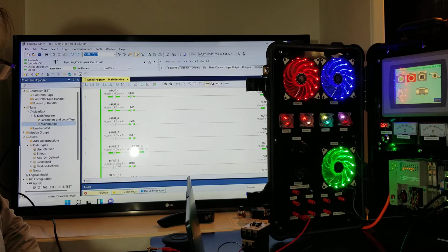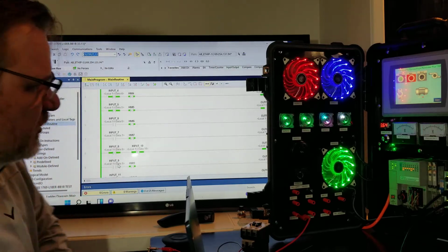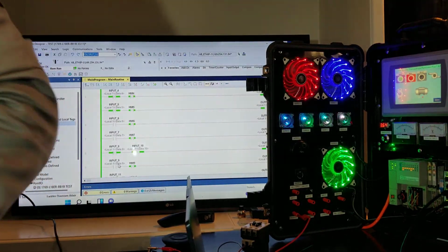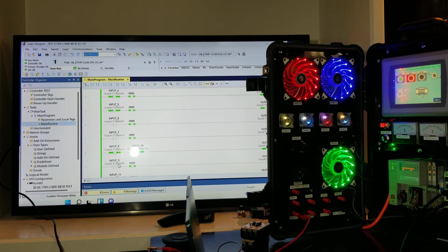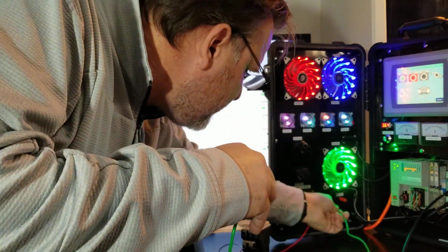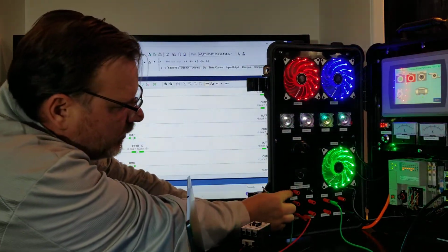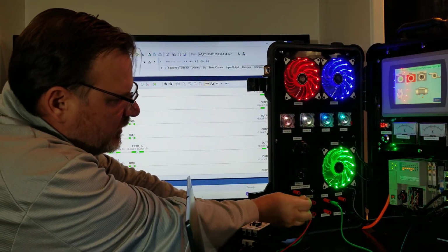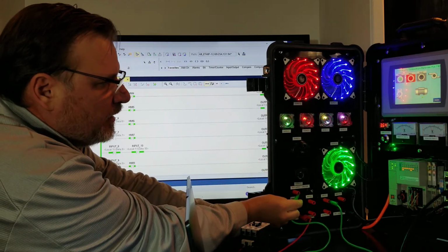Okay. Output 9 normally takes input 9 to trigger it. So let's fire off our input 9. What I need to do is go ahead and create an input link. So input 9, and then we've got our 24 volt coming in, and once we do this, it's a lot like just a switch, turn it on and off. Can you hear that?